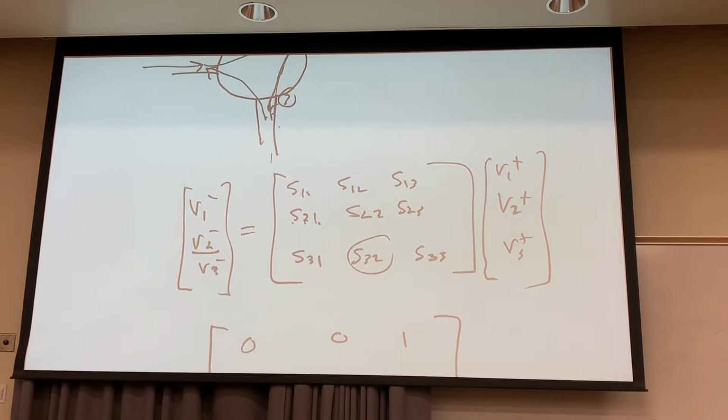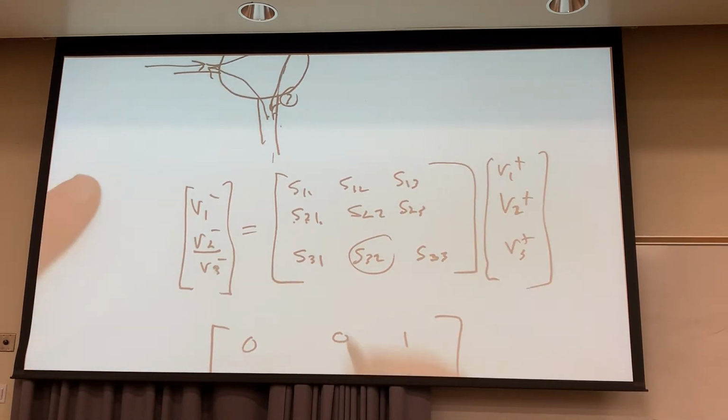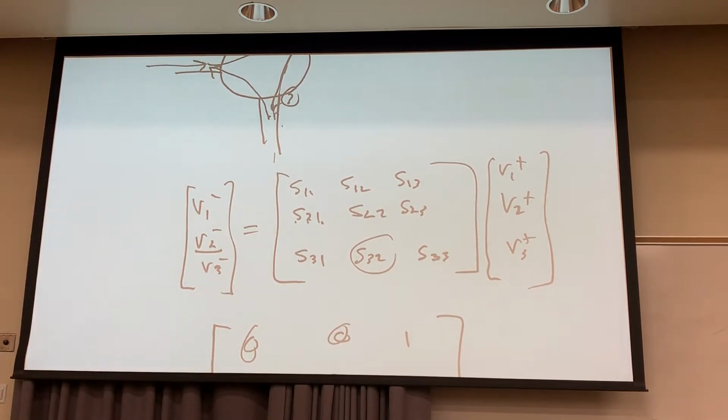Yeah, and that's the ideal. Now the real. In truth, you can never get this, or this, or this, usually. You can't get 0. Normally they measure these in dB, but you can get a factor of 1/10,000th, or 100,000th, or 1 millionth. If you think about it in dB, 1,000 is 30 dB, 10,000 is 40 dB, 100,000 is 50 dB, 60 dB is going to be 1 million. Usually 60 dB to 100 dB of isolation between these ports, meaning this.